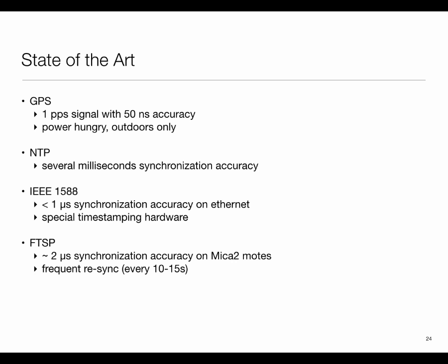So GPS, although we think of it as geopositioning, is really a geopositioning and timing system. That's really what it is. All GPSs internally calculate time relative to the atomic clocks as a necessary part of localization. And in fact, many of these devices have a pin called the PPS pin, 1 pulse per second pin. Essentially, the pulse on that pin is synchronized to the global time, and it's usually accurate to within a few tenths of nanoseconds.